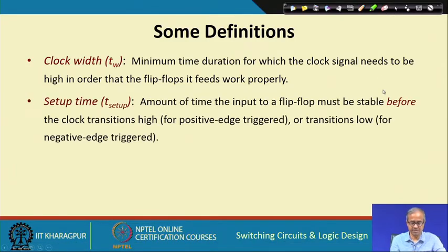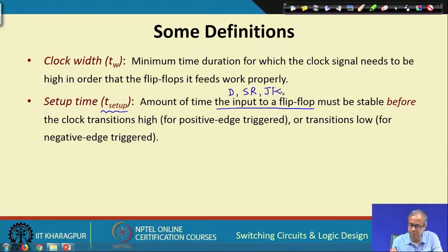Then we have something very important, this is called setup time. I shall be giving some examples later, but let us look at the definition. We designate the setup time by T setup. This is defined as the amount of time the input to a flip flop, and input to a flip flop means it can be a D input for a D flip flop, it can be S and R input for an SR flip flop, J and K for a JK flip flop and so on, the time the inputs of a flip flop must be applied and must be held stable before the clock transition comes.